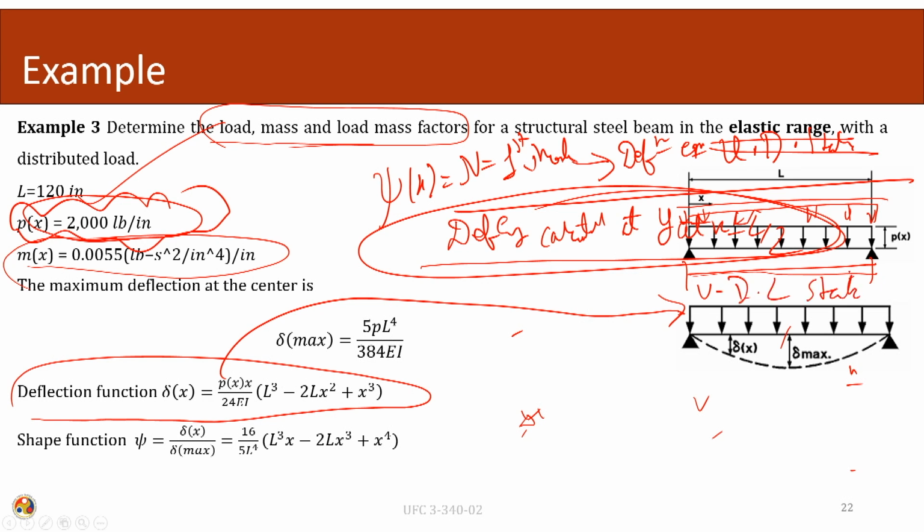I can use the same nomenclature as P, or some other nomenclature such as Sx also, but the point here is that this is just to cause this shape, and this is mimicking the first mode shape. The chosen degree of freedom is at the center, so y is evaluated at x equals L over 2.